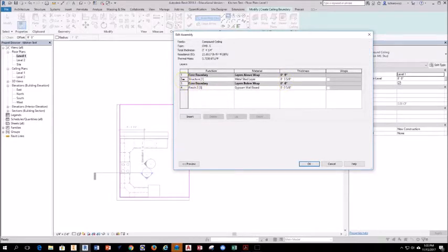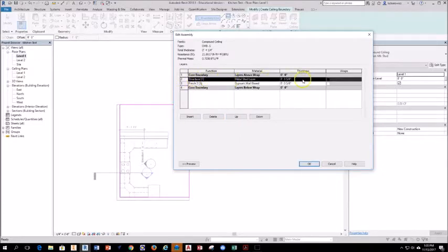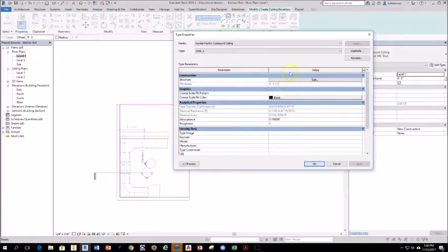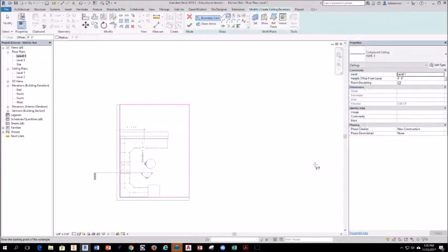I really do not need to have any metal structure, but I am going to have something in this core boundary, because I don't believe it'll give me just a finish. So I'm going to move that up, and delete this structural layer here. So instead of having a 5/8 thick drywall, I'll make that a 1/2 inch thick, and it's gypsum wallboard. Then go ahead and hit OK, and I have a 1/2 inch thick ceiling. Okay, that's going to be our ceiling. I'm going to hit OK.